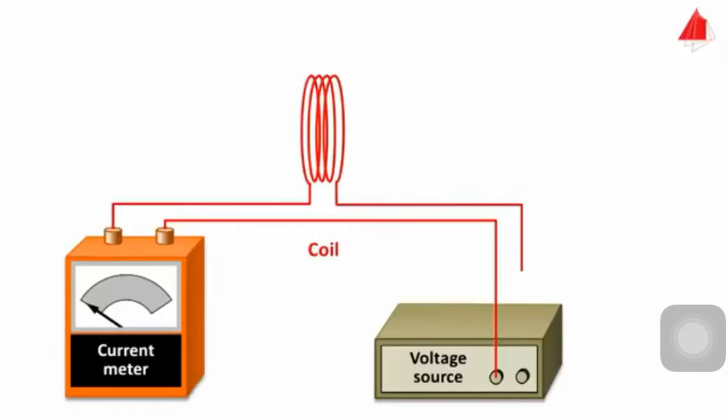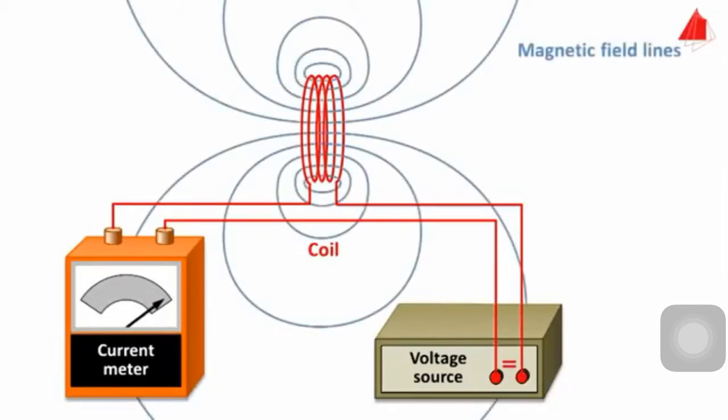The animation shows a coil, which can be connected via an electric current meter to a voltage source. After applying a direct voltage to the coil, the electric current first increases fairly quickly, then more slowly, according to the inductance of the coil. Eventually it reaches a level resulting only from the ohmic resistance of the coil. The current creates magnetic fields that flow around every small piece of coil winding. The individual fields superimpose and form the total magnetic field depicted here in blue.